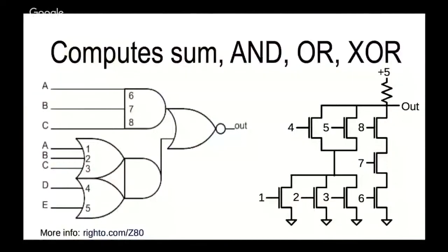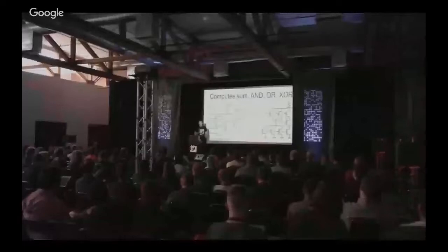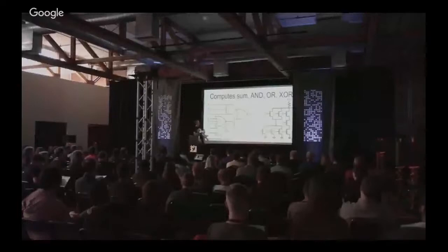These 2 gates, you don't require any circuitry. They're just made by wiring the 2 parts together. So this is one of the ways that made the Z80 much more compact. I won't try to explain what this is actually doing, other than it takes ALU inputs B and C and then computes the right operation all with this one gate.